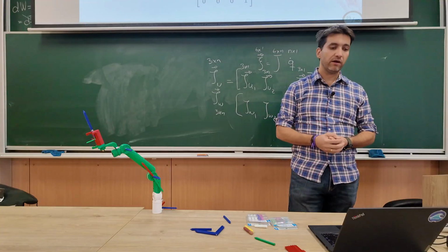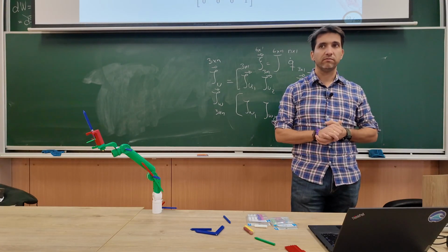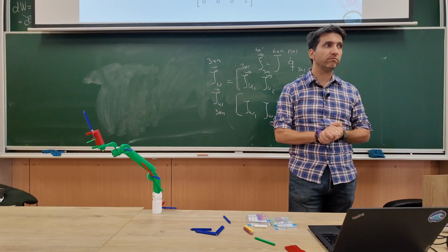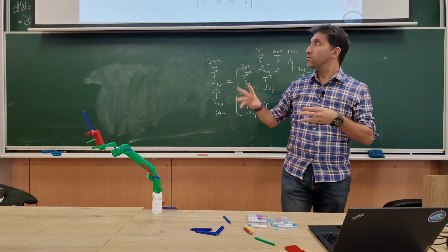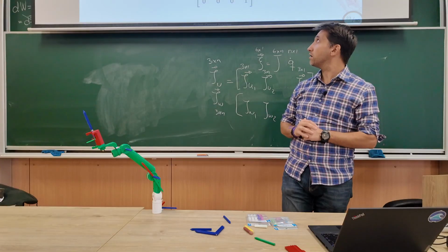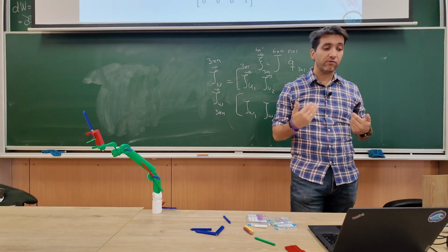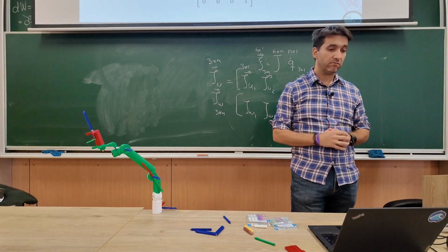Add them all together, and I have my Jacobian, okay? Which is what you will have to do in the lab, for the robot in the lab. You have the DH. We'll also give you the transformation matrices so you have them cleaned up, and then you will have to construct the Jacobian using these rules.